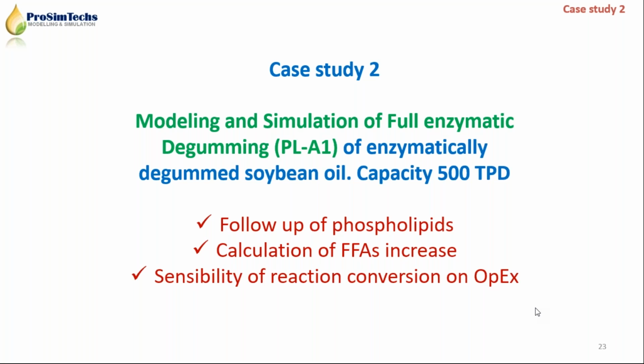We are going to see again the phospholipid follow-up to determine oil loss, how to calculate the theoretical free fatty acid increase according to the phospholipid profile and content in the degummed soybean oil, and of course according to the enzyme performance, and finally an operative comparative analysis when we face some problems again with the enzyme dosification.